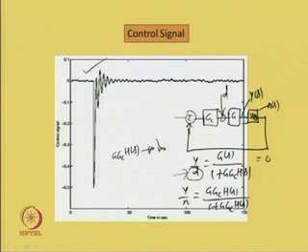But when G GC HS is very high, look at the second transfer function, then in that case it will be approximately 1. That means the output y will be equal to n. Therefore, the effects of measurement noise will be very much present in the output of the closed loop system. Thus, it is not possible to design a controller GC which will give us satisfactory noise rejection as well as static load disturbance rejection. So, one has to have some compromise while designing a controller for rejecting disturbance in the system.